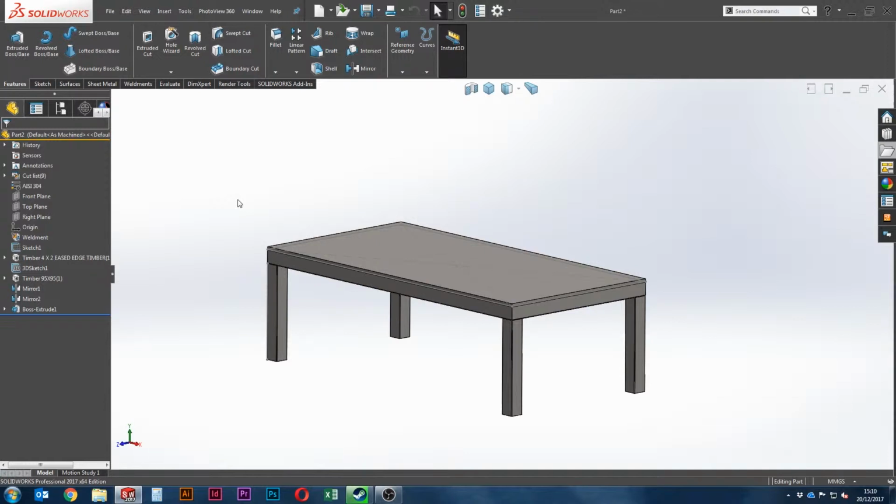So the basic essence is that you can use 2D and 3D sketches to define your basic model, and then from that model you can create structural members which contain groups of sketch segments. And then you can also add additional features such as gussets and end caps, especially if you're working with steel or with timber. You would tend to use weldments to create your models.